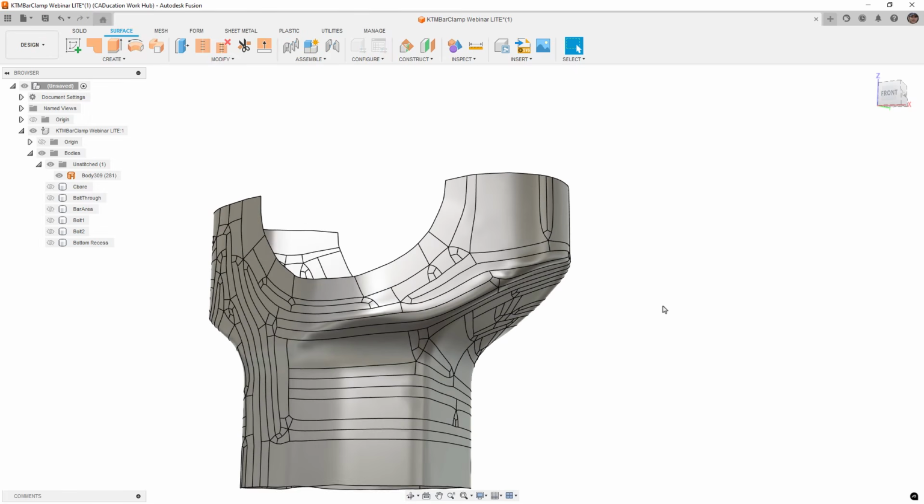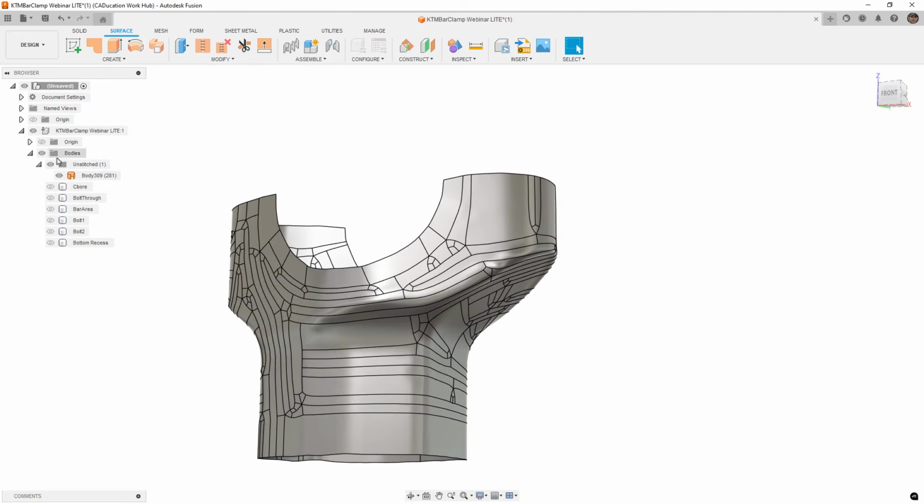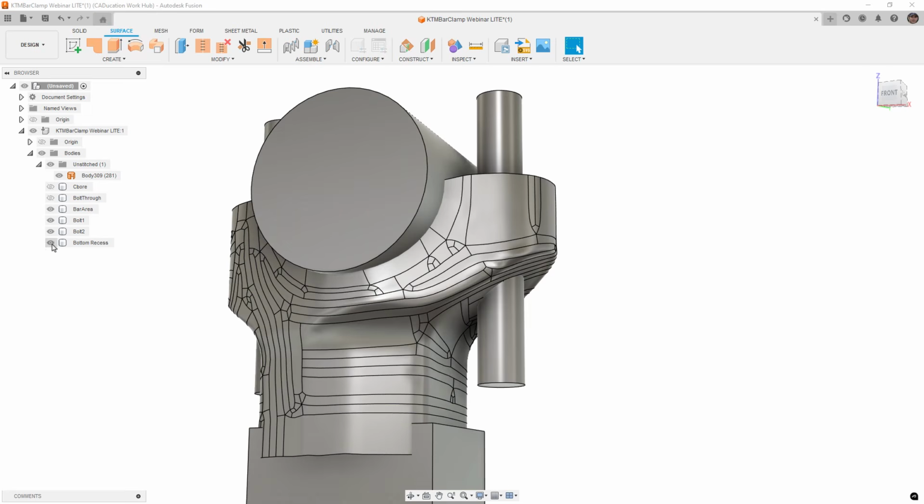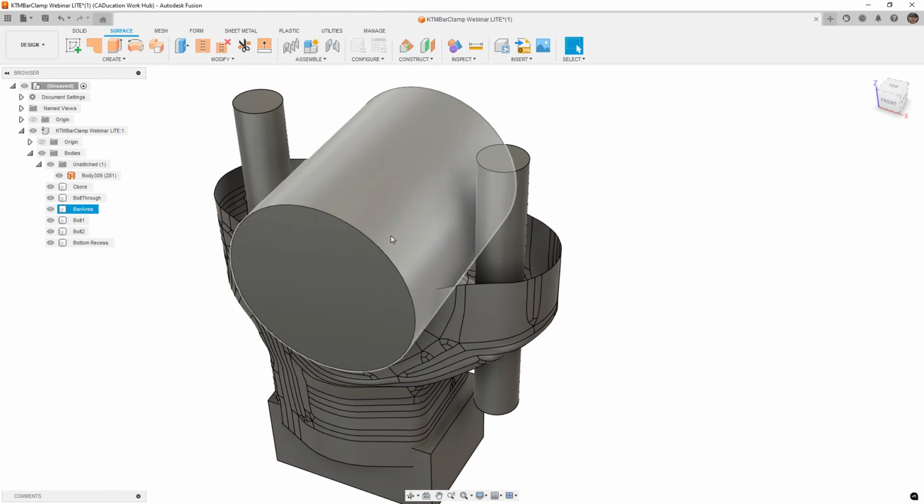But for the purposes of this, let's go ahead and talk about how we can build this into a solid body. One thing you'll notice is that we don't really have planes. The planes didn't come in as bodies that we would need to work with. So unfortunately, the way that we need to get around that is by creating surfaces from those planes. QuickSurface itself will be able to use those planes to cut things, but it didn't get brought in here.